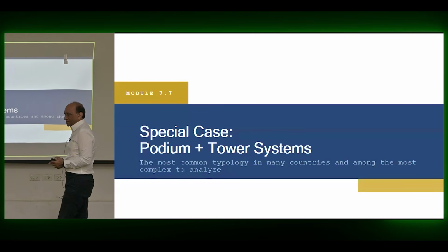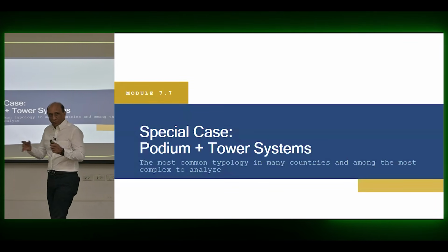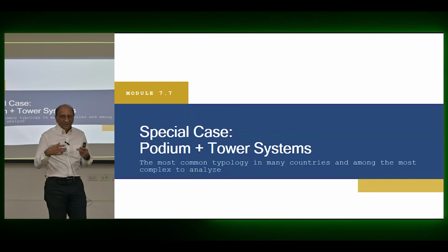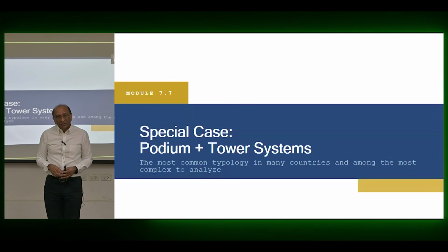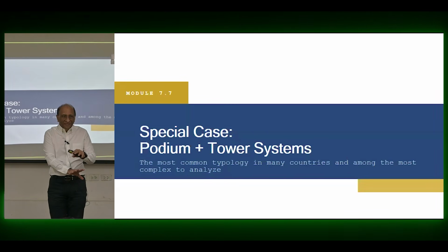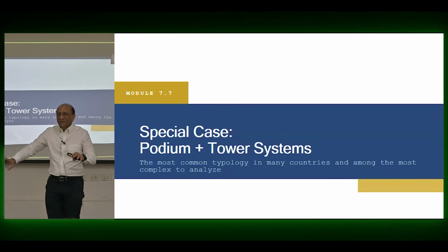Podium and tower system, another special case. I just want to go over and emphasize what the problems are. So podium and transfer has another story because of the foundations, which we will study next. Now loading is going to be different at different times during construction.